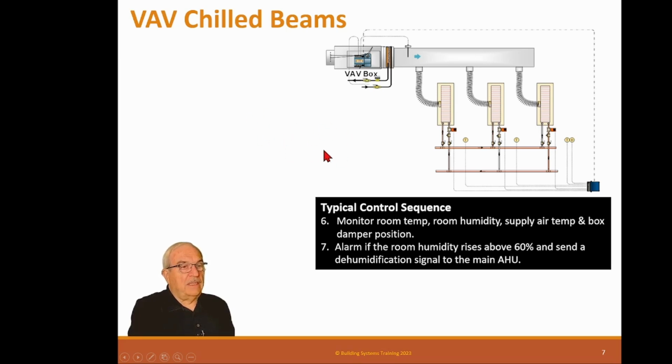This is the VAV chill beams. It's exactly like the chill ceiling, except it doesn't have a displacement ventilation system. It has a direct air system into the space. Now for the chill beam, chill ceiling panels, you could also use VAV to diffusers in the ceiling, but because we need all that ceiling space, we don't like doing that. We'd rather have them dumped out of wall grills.